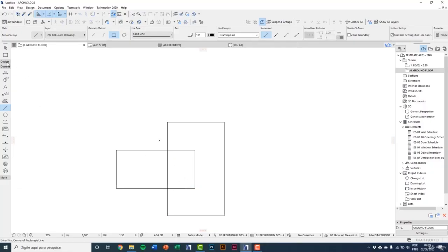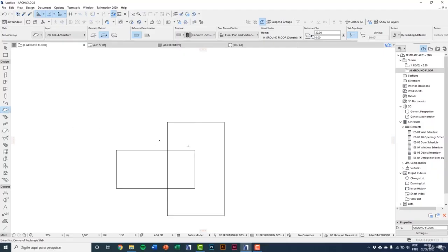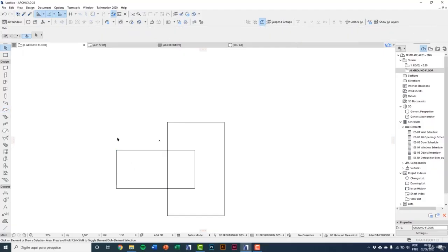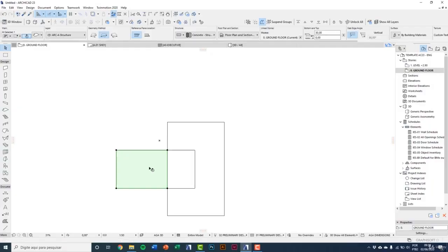I will select the slab tool, so go into design, selecting slab tool, and then I place the mouse inside this form and pressing space bar, the magic wand appears. You can see the blue outlines, so doing a click, a slab is done inside space. I make another slab here, so pressing space bar, I do a click, and then pressing ESC, I come back to selection arrow, and so I can select these slabs, pressing shift. It's not easy to see it because they are white.